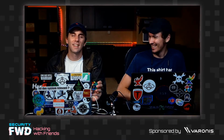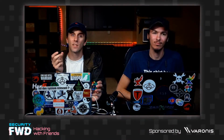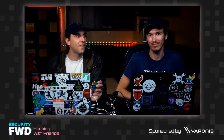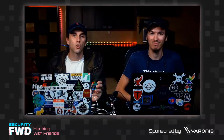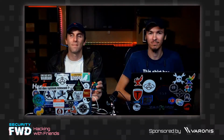Yes, you can, but you have to solder a 0 ohm resistor that's the size of a grain of sand. So if you're into that, then yes, you totally can. It does require a little bit of extra work to use a directional antenna or a stronger antenna with these little microcontrollers. Although you can, it just takes some very, very small soldering.